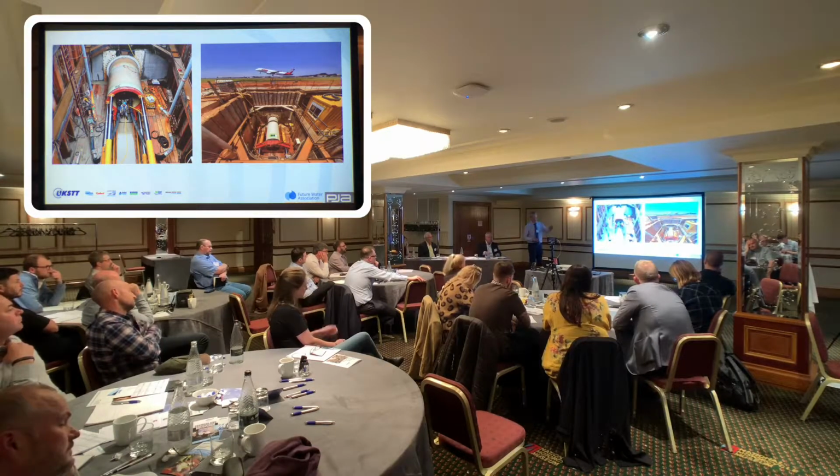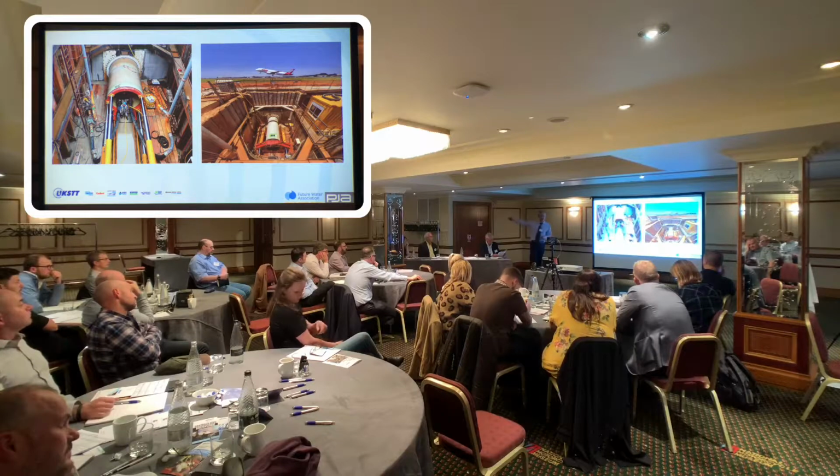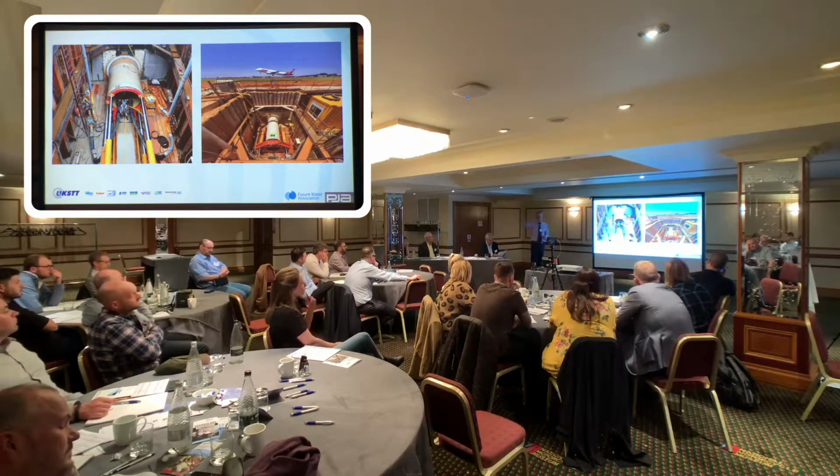Just back to the separation plant, one of the problems with losing lubricant into the shaft is that you often have your pump in the bottom of the shaft going back into your separation plant, and some of the lubricants that are used are also flocculants. So you might actually end up overdosing your settlement system without even knowing it if you're losing lubricant.